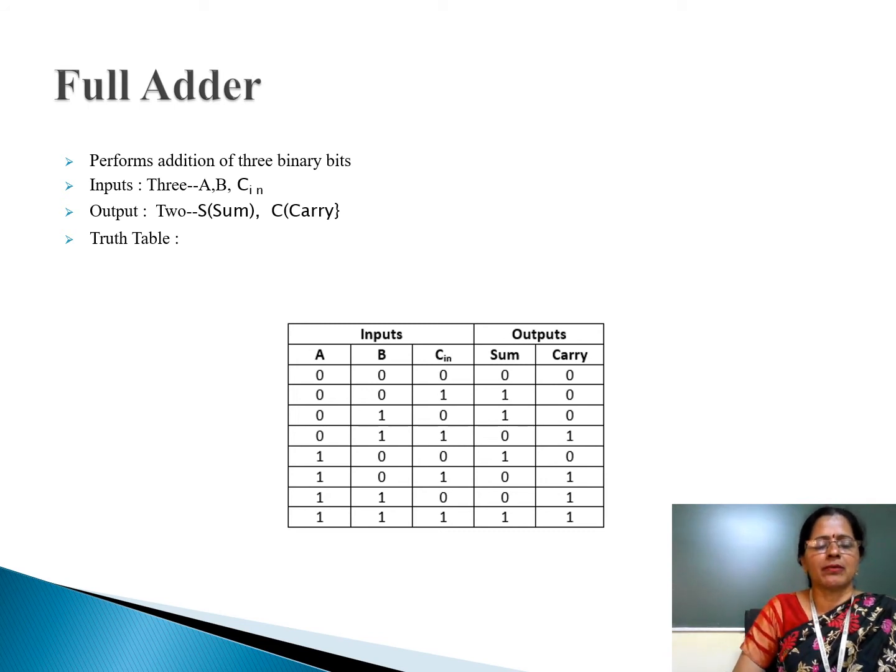Then next we discuss the truth table. Since there are 3 inputs, accordingly we have 8 states starting from 0, 0, 0 to 1, 1, 1. For each state we have a sum output and also a carry output. How do we determine the sum output and carry output? If we are able to determine the values manually, it is not required to practice the truth table or memorize it by reading repeatedly. We can write the truth table by a manual process, then that truth table can be implemented to logic circuits. So let us check any 2 to 3 states, then the rest you can try.